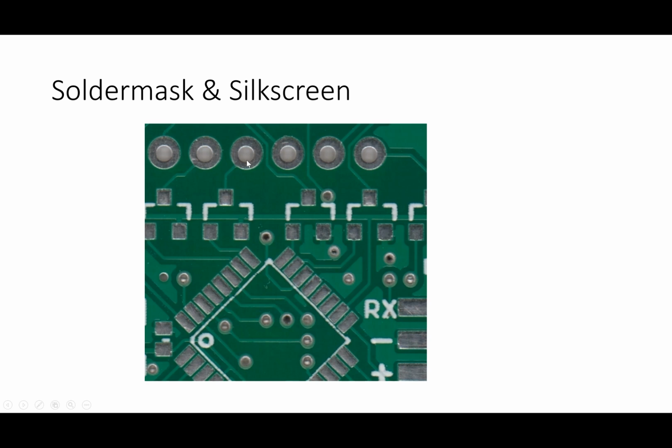And so in this particular case, I've got 2 types of pads. I have these annular rings, which are around what I call a plated through hole. So a hole that's been drilled through the board and is plated with copper all the way through the board. Those are the sorts of things that we typically solder to. Now there's another type of through hole that we don't solder to. That's called a via, and this is a via right here. What that via is doing is it's connecting one layer to another. So it's connecting a wire on one layer to another layer.